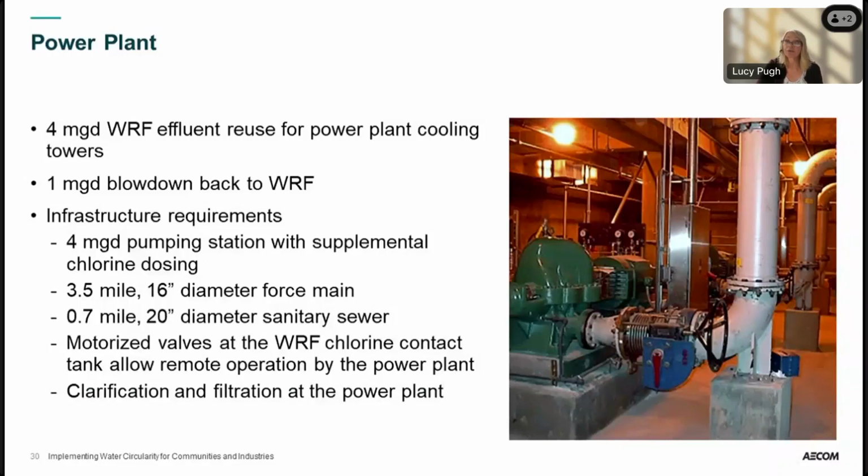And so the power plant turned to the community's water reclamation facility as a water source. They needed 4 million gallons per day of effluent to supply water for their cooling towers. And in this case, the community was able to accept the blowdown from the cooling towers back at the water reclamation facility. So that was a nice arrangement.